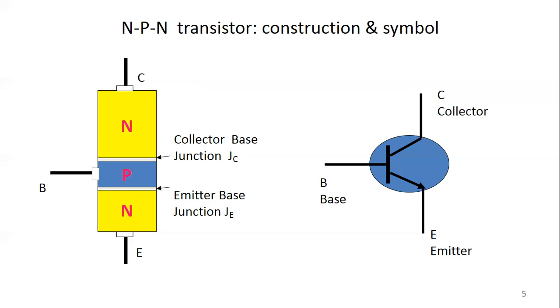What we expect is that we have to control the maximum charges or maximum current. So what is happening? The emitter is going to emit the charges, and whatever charges are emitted will go into this collector. At the same time, whenever the charges are moving toward this collector, they are passing through the base region. So a smaller amount of charges are going to recombine with the holes in this base region, means the electrons present in the emitter region are going to recombine with the minority charges present in the base region.